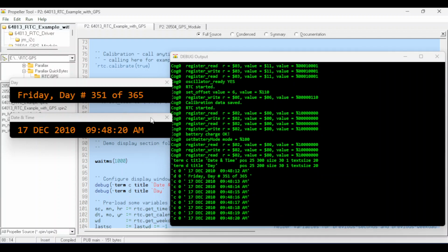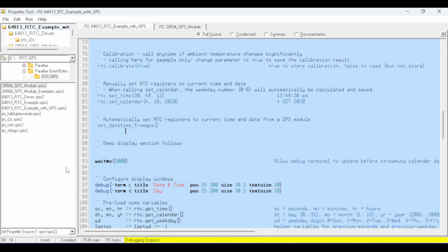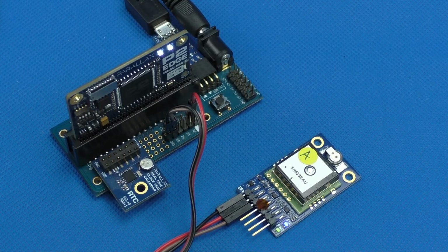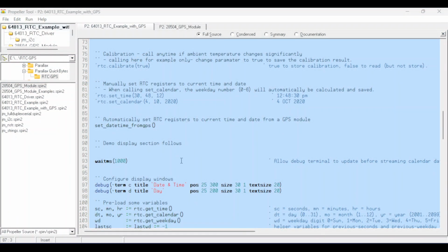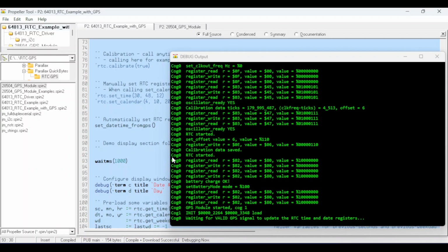Obviously that's just a bogus date I've put in. Now I'll just close that and I shall uncomment that command, so it will set from GPS. We'll just quickly flick to the camera view, make sure we've got signal. Yeah, blue LED is on there for the fix, so we do have a current valid GPS signal. That is important. And yeah, just press F10 again. I'll just reload that code. So hopefully this will all work.